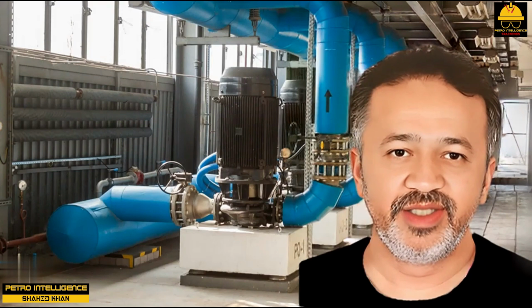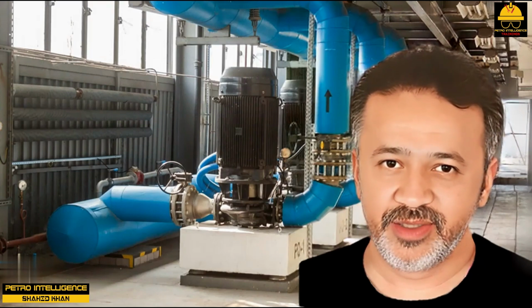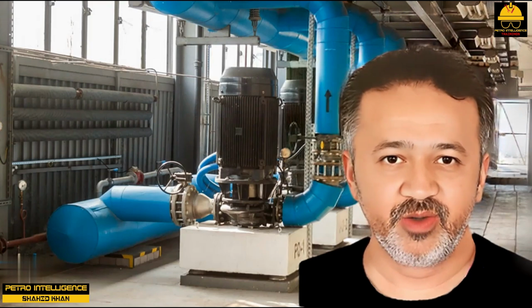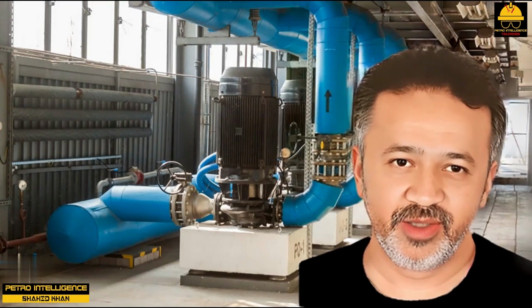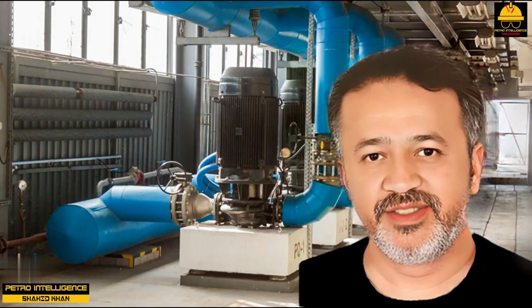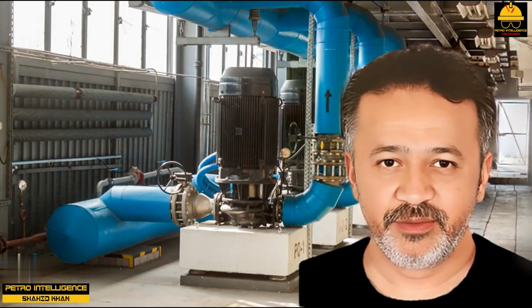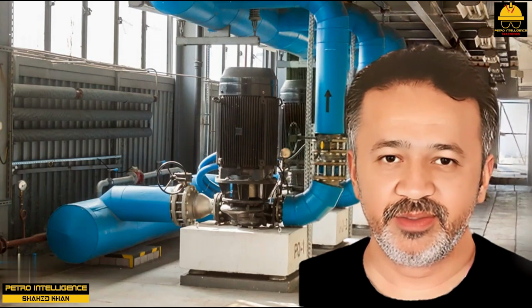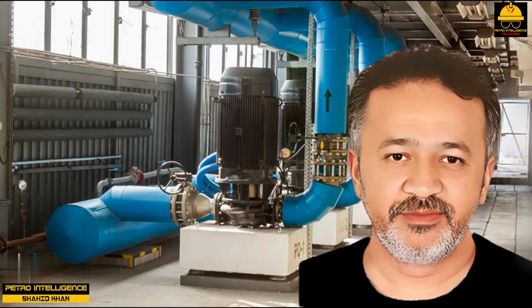This procedure is a lot of work and is often neglected by the maintenance department, who do not consider this work to be part of their job description. If the pump is driven by a steam turbine, the pump speed could be lower than in the design. Available NPSH may be marginal. Watch my video on centrifugal pumps, suction pressure limits.